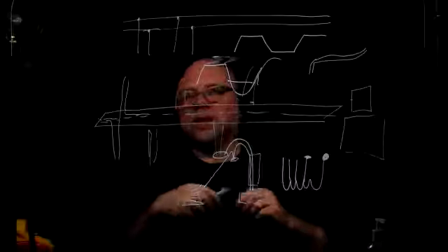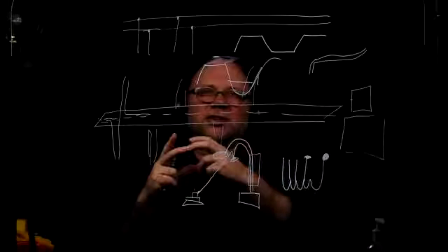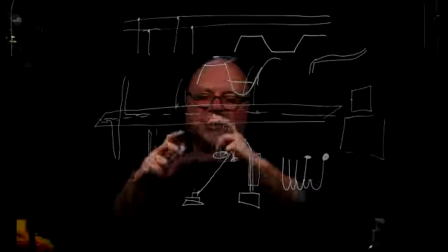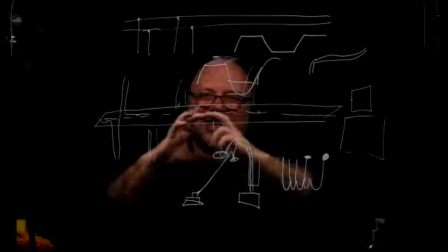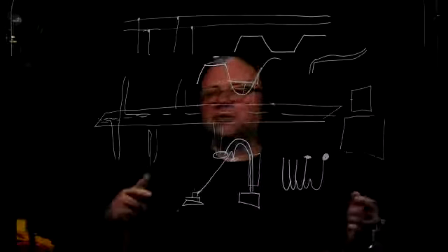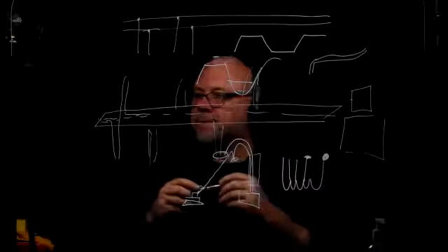Also, sometimes if you put too much DC signal through a coil, there's a possibility of the coil becoming egg-shaped by the forces involved, and that is going to rub against the cylinder and can also get damaged physically. You don't have to supply too much of it in order to damage the coil. Right? That's cool.